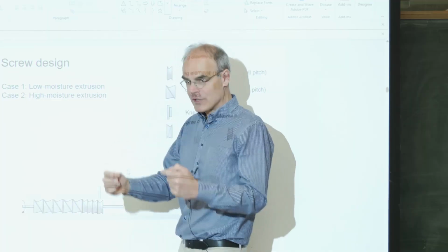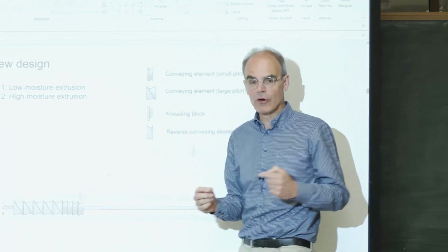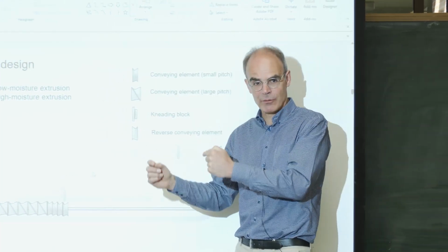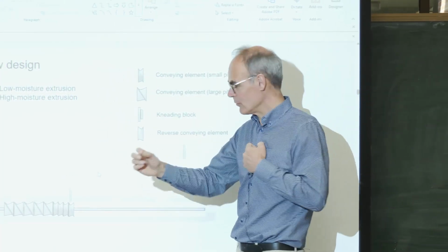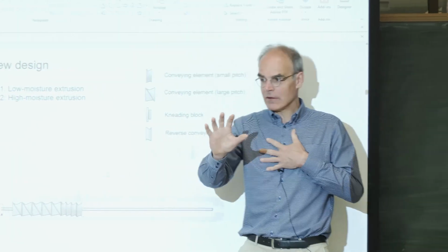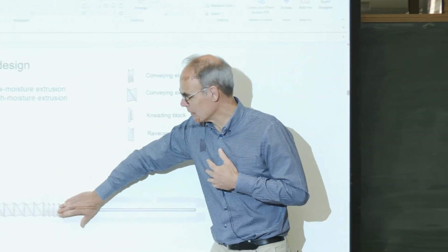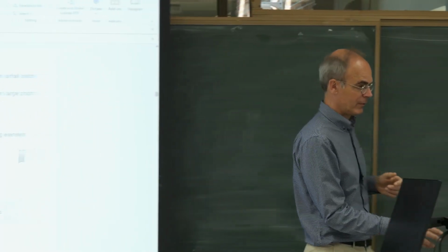So for these materials, both for starch and proteins, you first want to really soften them up. You want to gelatinize your starches, denature and soften your proteins. So you want to really get to a temperature of 80, 90, 100 degrees centigrade before we start really kneading. We're not yet here, so we keep on transporting it.